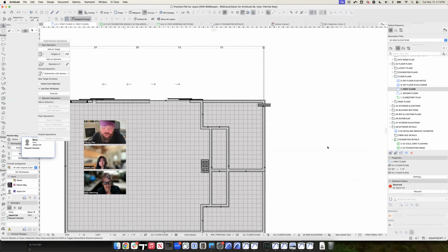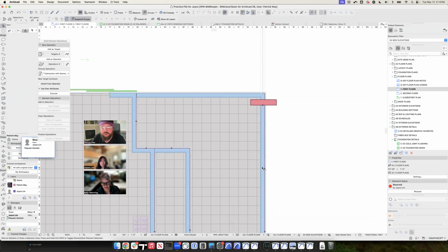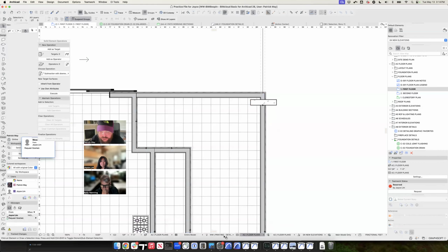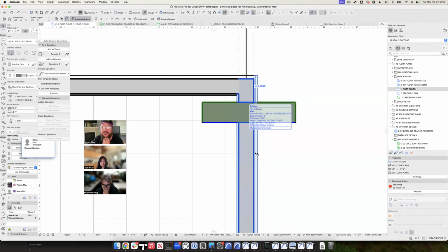So when you're driving around a model, the pen weights are always the colored. Do you ever want to look at the drawings as if it's going to be presentation mode? Yeah, only when you're on the paper space, or I'm using the wrong words, but you know what I'm saying? Yeah. In the view, a lot of times, I don't really use the detail pen set unless I'm drawing details. But a lot of times I'll just work in the document pen set because the colors are distracting. At the same time, it does give you an indication of whether or not the pens are correct.